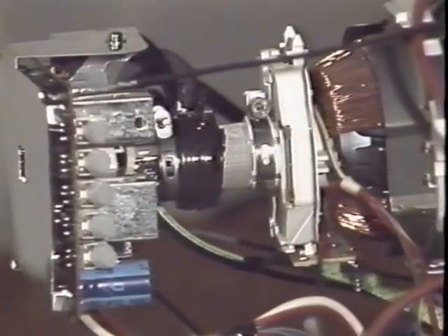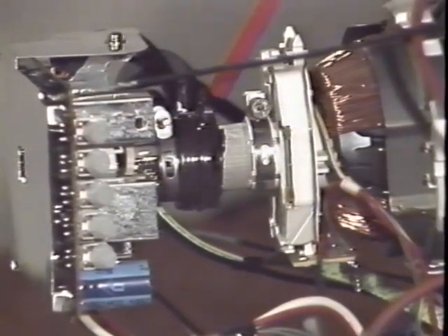If this adjustment is incorrect, the edge of each white area of the screen will have a border of one or more colors. Colors that require more than one gun to be on will also show incorrectly colored fringes. There are two parts of the convergence alignment. One, called static convergence, affects the center area of the screen and is performed by adjusting two sets of magnets.